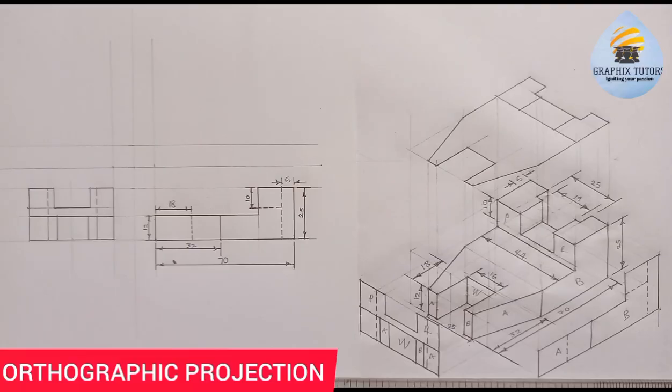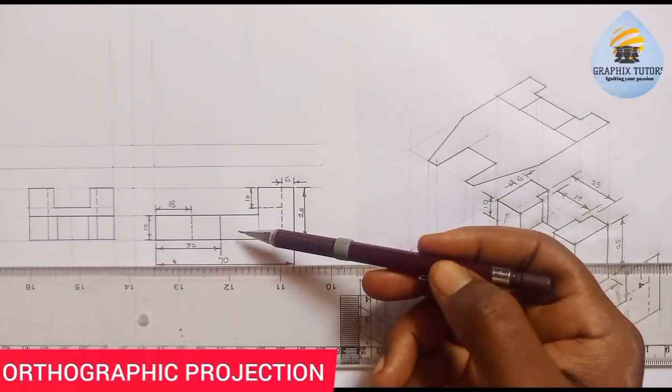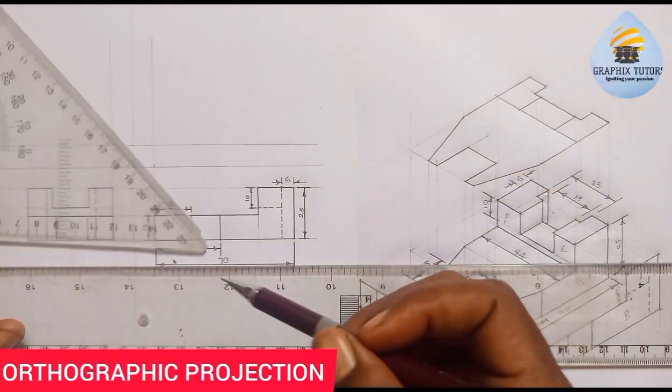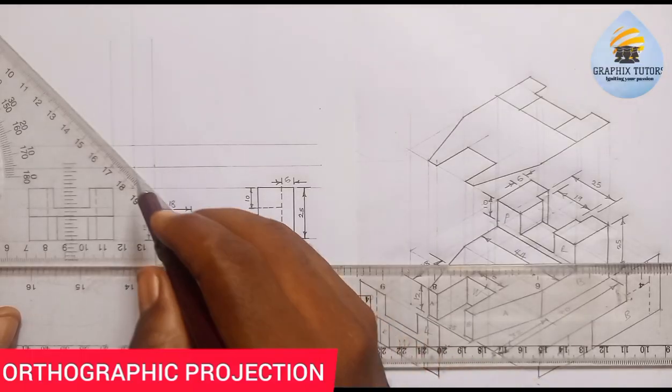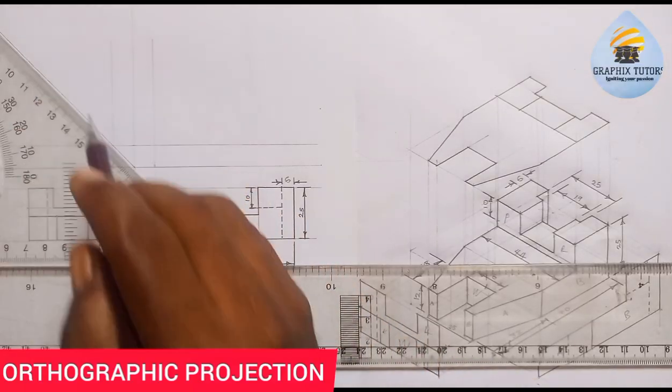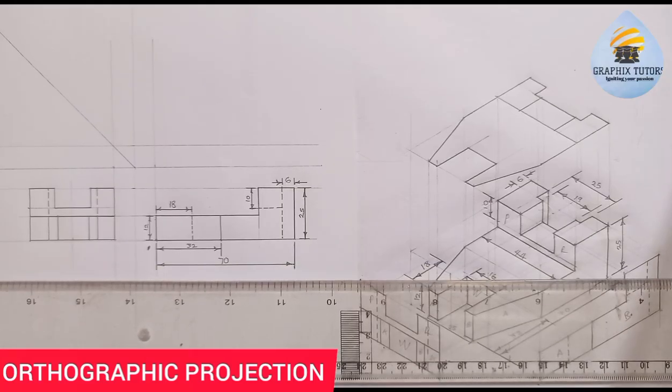So the first thing you do is just to take your instrument. Just know one thing, that the plan is always on top of the front elevation. So you just come here and you draw your 45 degree here in this fashion. Can you see that? And the next thing is you just project your points.